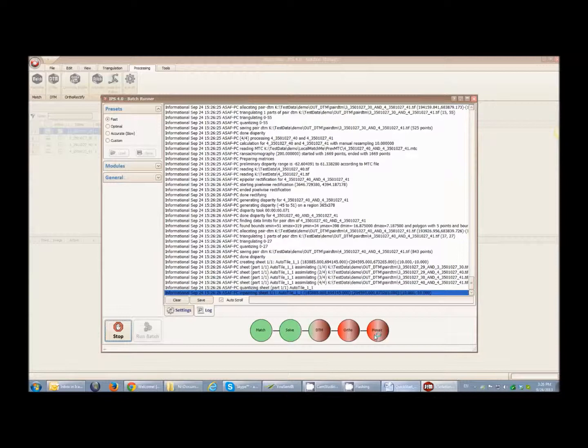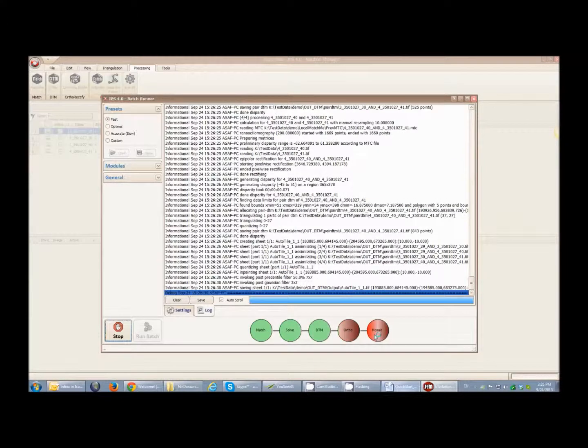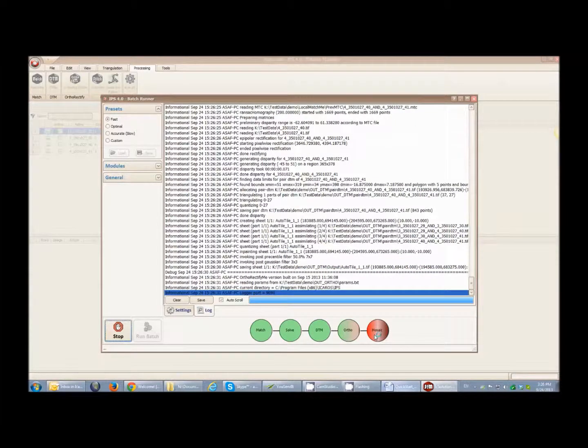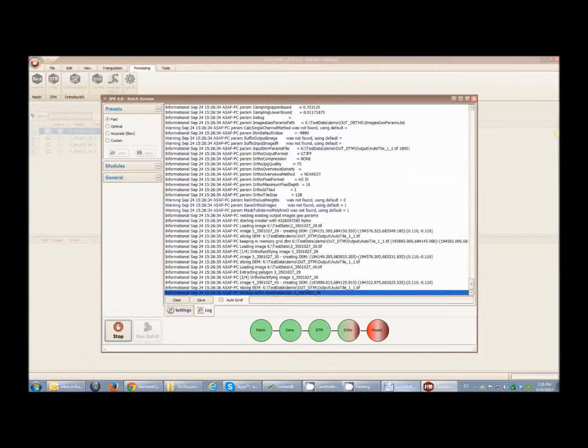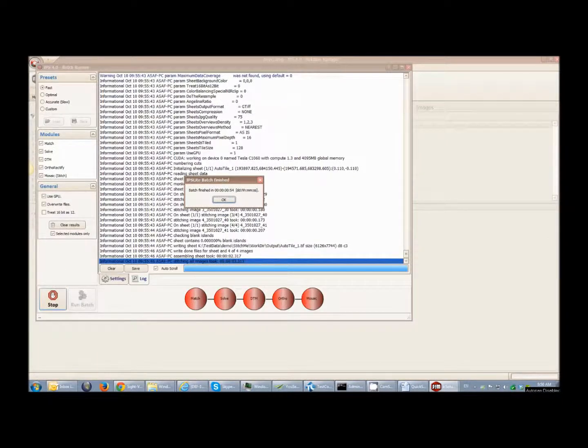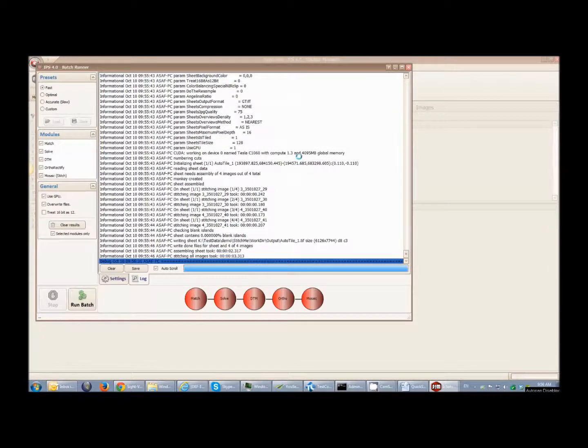Please keep in mind that the mosaic created in one of these modes is highly dependent on the integrity of the input data, and that some projects may need additional manual editing and processing. One of the great benefits of using the fast option is the quick processing time, about 1 minute for 4 images in our test project. Once the process has finished, close the batch window. The output mosaic will be shown in the GeoViewer.